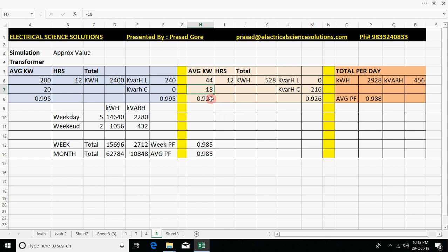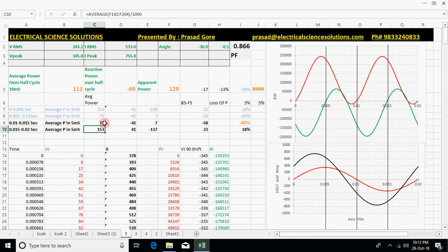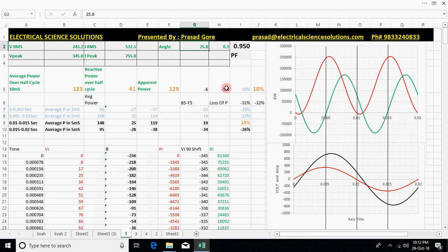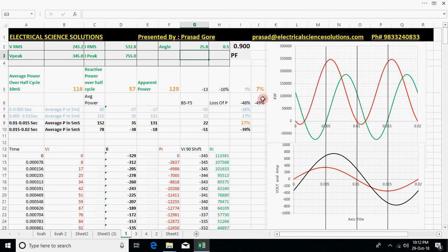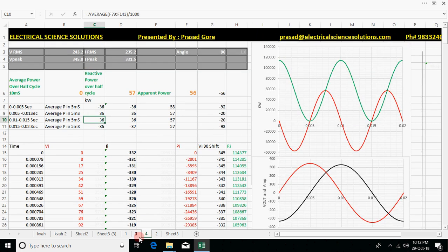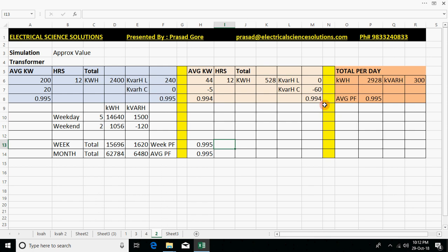So it can be worse than this. It can be better than this. If you have just -2, or you can have just -5 kVAR as the average, you are having 0.995, wherein you will get 3.5%. Now another point I just missed earlier: it was 18.2, no, it was 25.8, that is 90.7% was given, but now they are reduced to 3.5% because maybe now, as I said, they have started counting kVARh leading also. So for this 0.995, they have just made it half because the contribution of kVARh lagging and leading will be equal. That is maybe the concept behind getting to 3.5% now.